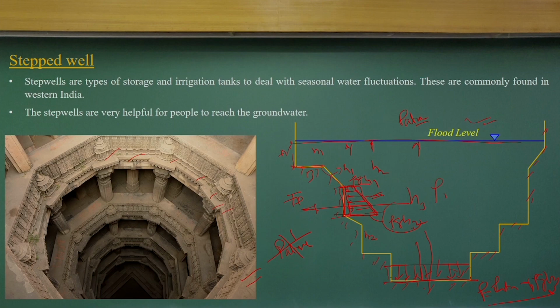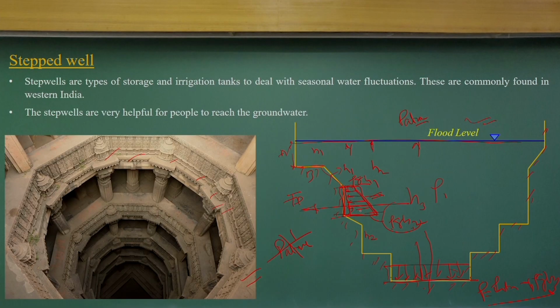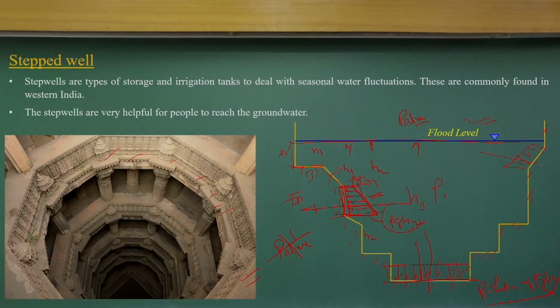Now, another point comes up: where does this force act? The location of this force is the center of pressure. We can compute the center of pressure very easily, and I will demonstrate it to you. When you have an inclined surface, we can also determine the pressure diagrams. The pressure will be similarly trapezoidal, and normal to this inclined surface. Again you find the area of the pressure diagram, or you do the integration, to find the force acting due to the pressure distribution, and you look at where the center of pressure is, the point at which this pressure force acts.